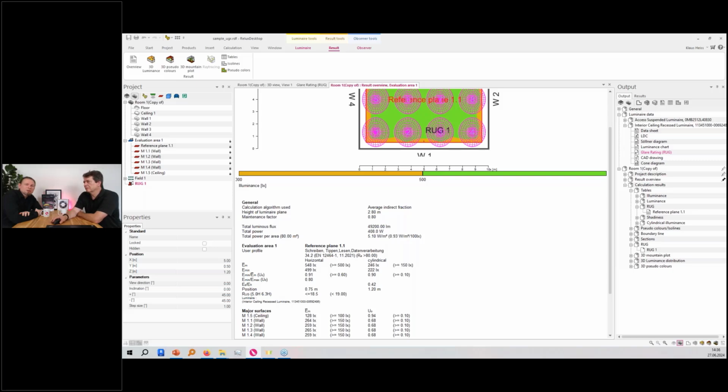Of course, I do not need to tell you, glare is also something quite individual. So a UGR value of 19 does not mean that you are not glared. If you are a sensitive person, it is really personal. That makes it really hard for planning. But it's just in comparison.